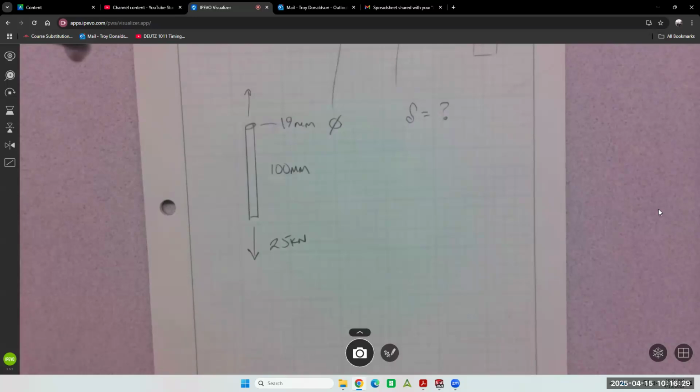That's a big concept that I'll emphasize a lot. You've got to check your stresses first and then realize, oh, this is good, it's within stresses, I can calculate more things. If you check the stress right away and it's not good, it's outside the limit, then you're done. You don't have to check the deformation. It's not safe. I can't do it.